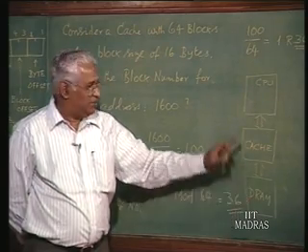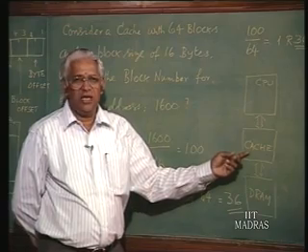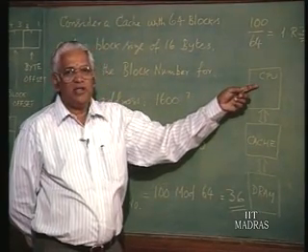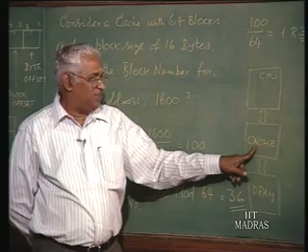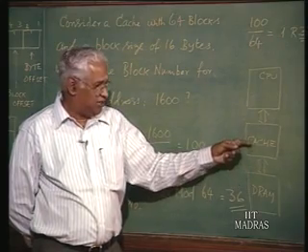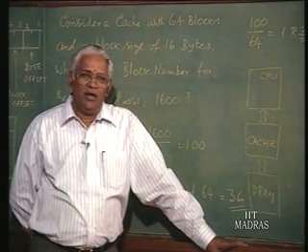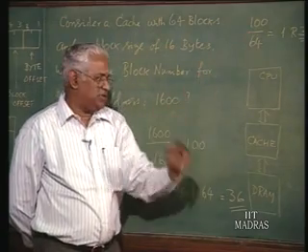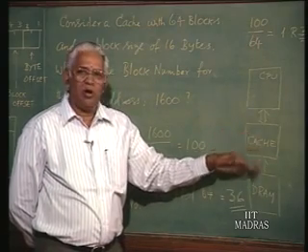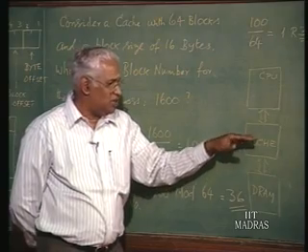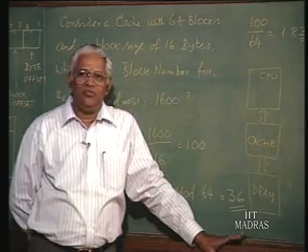Agreed? When the CPU writes something into the cache, after all from the CPU point of view it is just a memory, it can read or write. Now, in this particular case, if the CPU writes into the cache, what happens? Then there will be different data in the cache, different from what was in the original memory. The situation is not bad. At some point in time, the cache content will be removed, and in that particular block another data may come. At that instant, the modified cache contents can be written into the DRAM. This is one way.